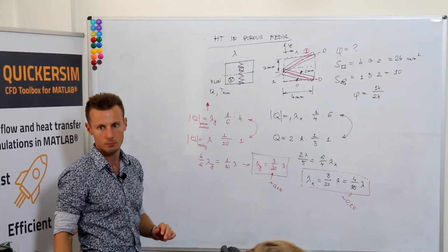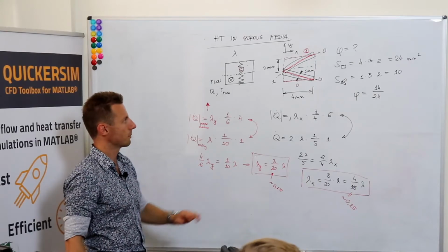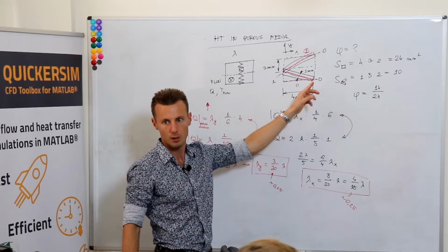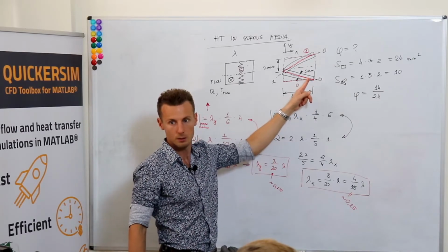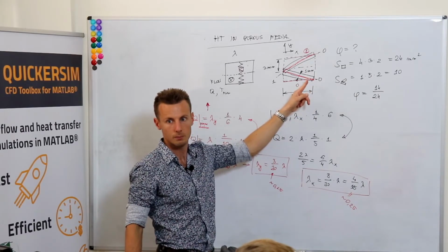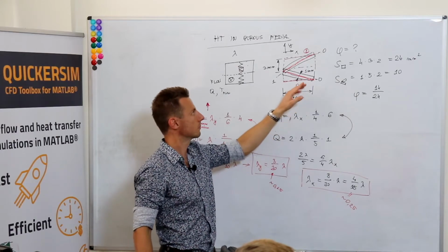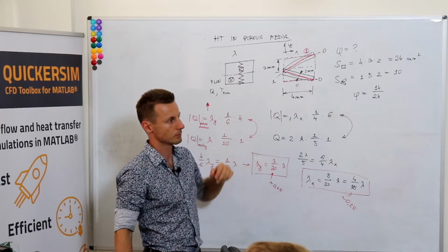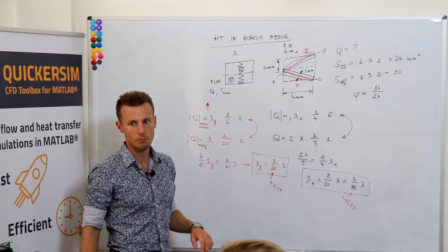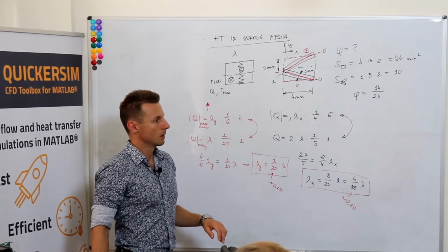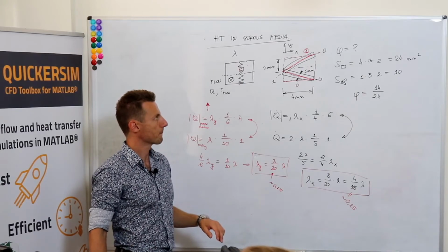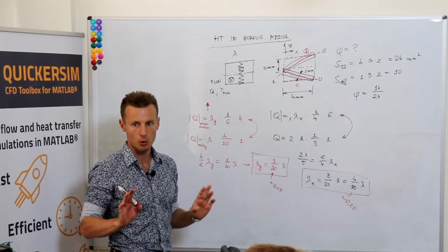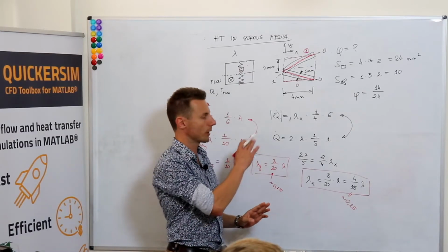Why do we do it along this path? Because there is no other way for the heat to move. Why does it not move from left to the right because the temperature is higher? Because we are assuming that the air can be omitted in this case, so the only way for the heat to move is through these metal fins, and we ignore the air because of its heat conductivity. Or once again, why we are doing this derivation process.